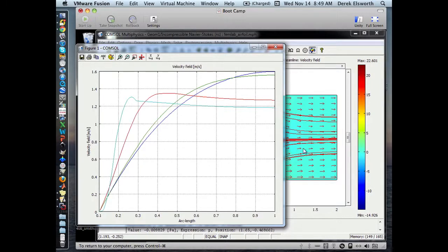These are values for different values of viscosity. In each case, we're using the same value of the flow rate coming in. The density of the fluid is 1 kilogram per cubic meter, which is basically air. The wing size is the same in each case. So by changing the viscosity, we're changing the Reynolds number. These are the magnitudes for different Reynolds number flows.